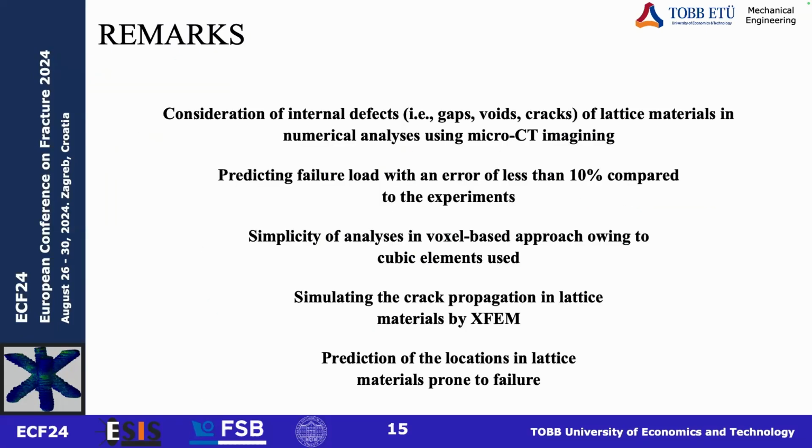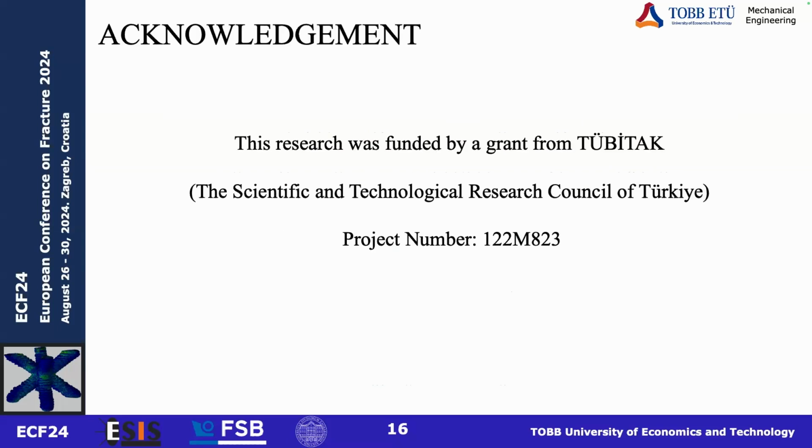And remarks and conclusions: consideration of internal defects, gaps, voids, and cracks of lattice materials in numerical analysis using micro-CT imaging and XFEM, predicting failure load with an error of less than 10% compared to the experiments, simplicity of analysis in voxel-based approach owing to cubic element use, simulating the crack propagation in lattice materials by XFEM, and the last one, a prediction of locations in lattice materials prone to failure.